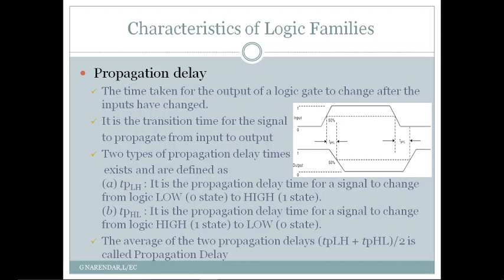This I define as the propagation delay of a logic gate. The output will appear some time after you apply the inputs, and this gap is called propagation delay. It is the transition time for the signal to propagate from input to output.